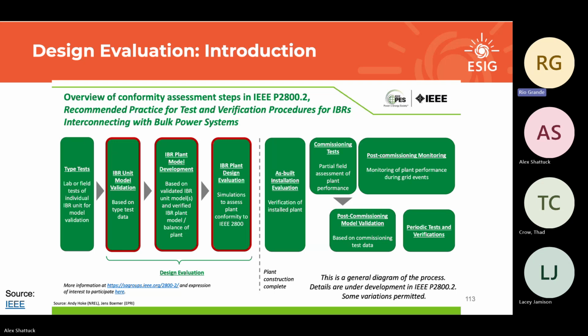So the other things are post-commissioning model validation. It goes along with testing. That looks a lot like what NERC MOD-026 and MOD-027, which is just MOD-026 now, would be. I think post-commission monitoring is just, if there's an event, get the data and run it, which is a really optimistic process, but it's in there. And then periodic tests and verifications through the lifetime of the plant, which all makes sense, but could be very difficult to implement in the regulatory sphere. But this is a good place if you want to have your own requirements or look to see what it takes to do these types of things, to go in and check out that language once it gets published.